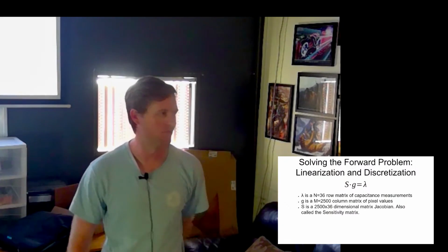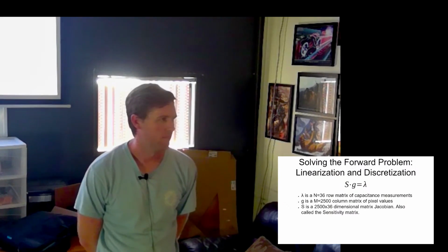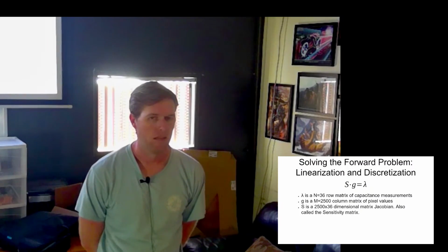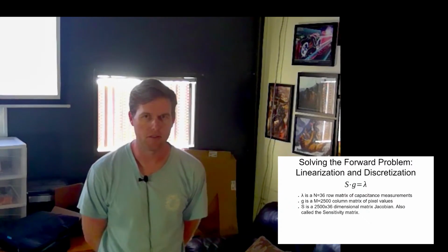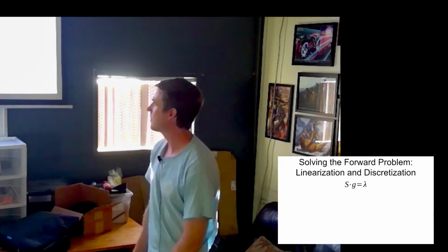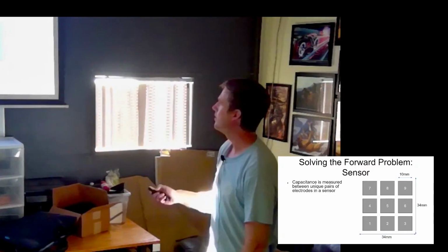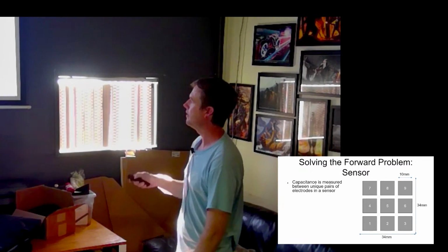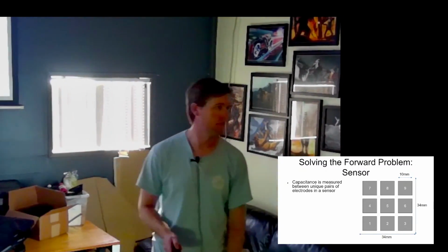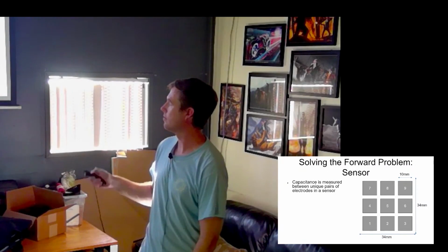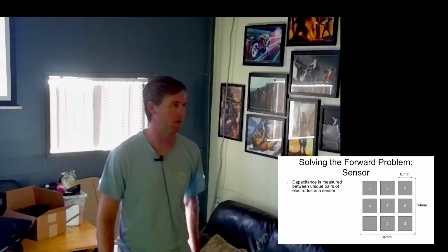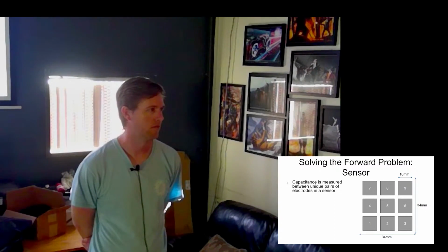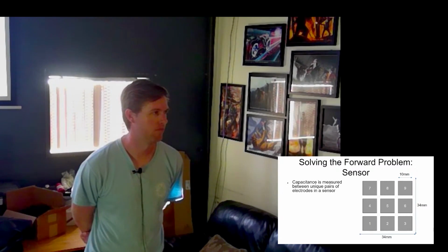Good question. I don't know if you covered this, but did you actually talk about what the probe itself looks like? You said you had coaxials coming out. Oh, yeah. The sensor itself could just be made out of a PCB. You could have copper areas arranged in a grid, and then have coaxial connections coming off the edge of the PCB board, and that would work as a sensor. Is there a reason you didn't want to integrate the sensors in there to get rid of the capacitive loading of coax cables?